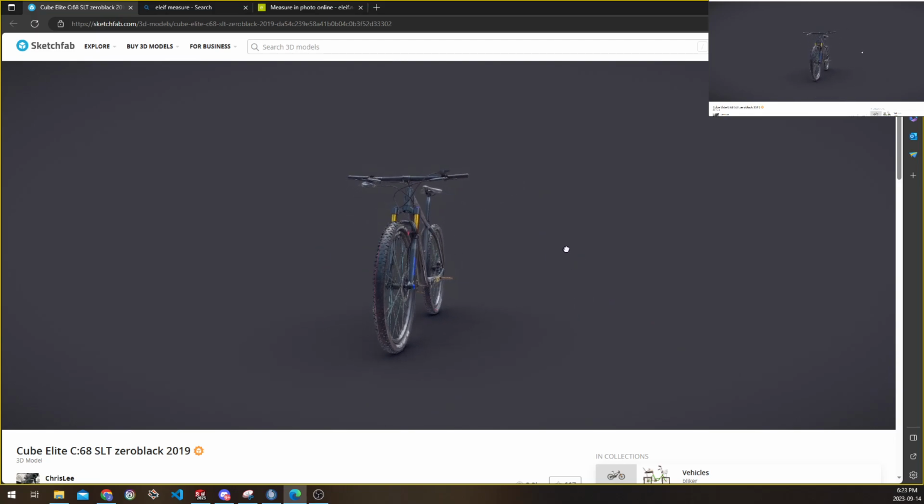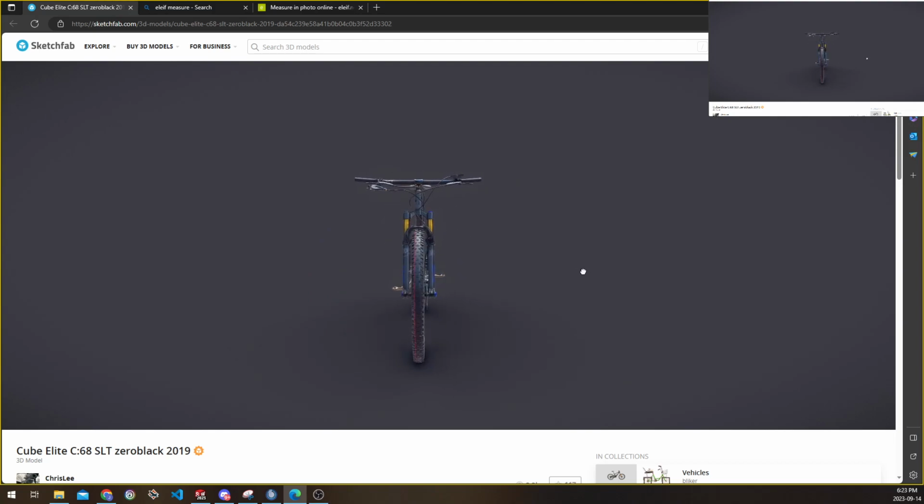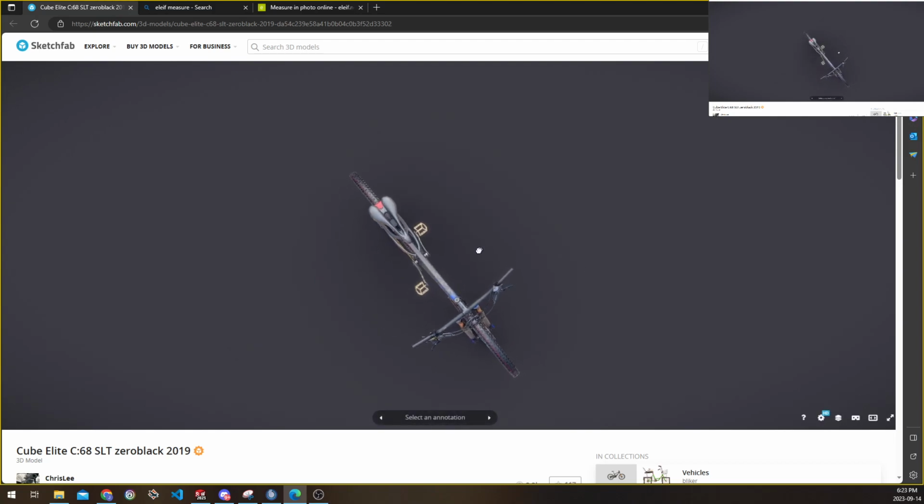Even though obviously the front of a bike, as most people would define it, is this, the most information that can be gathered from this CAD model is this face here. So if we were to define our kind of CAD space for this, this would be our front view, this would be our right view, and this would be our top view. Does that make sense?